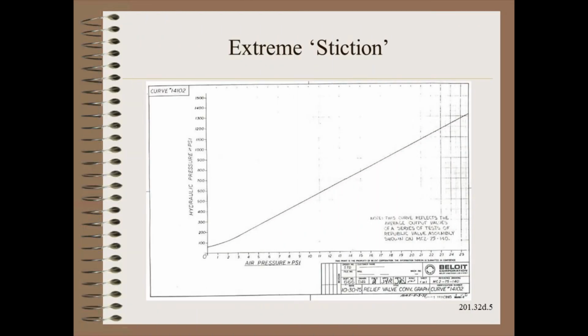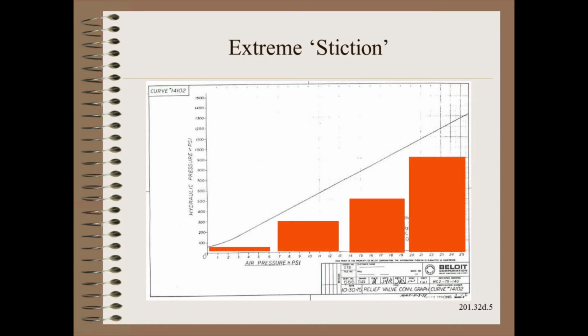You might find, as I have on several occasions, extremely poor valve response. It can be as bad as an output that goes in 3 or 4 steps, while the input is varied smoothly. A badly sticking valve can easily do things like this.